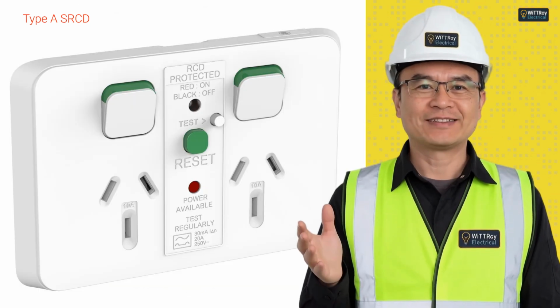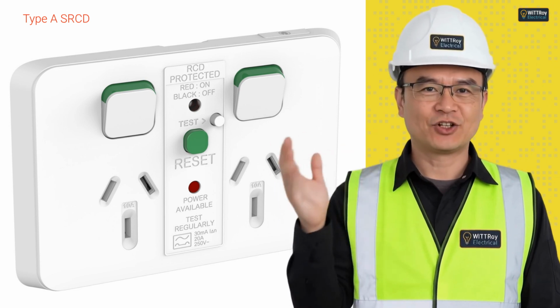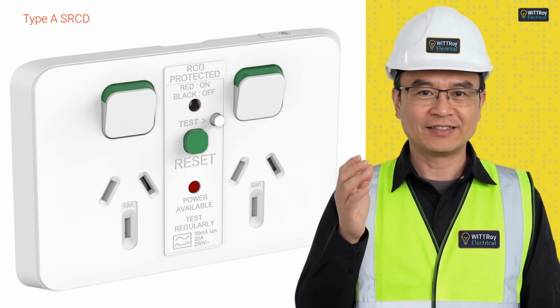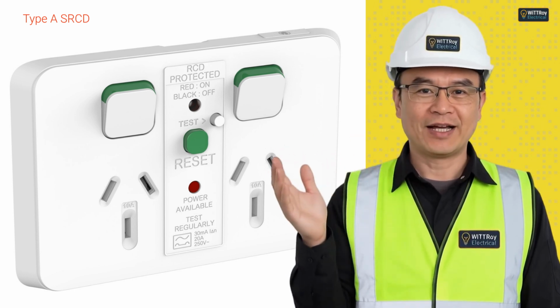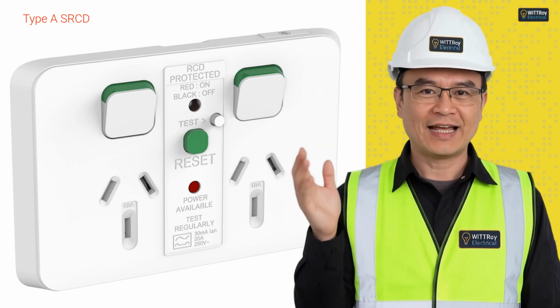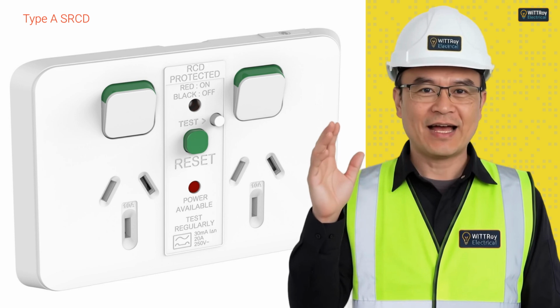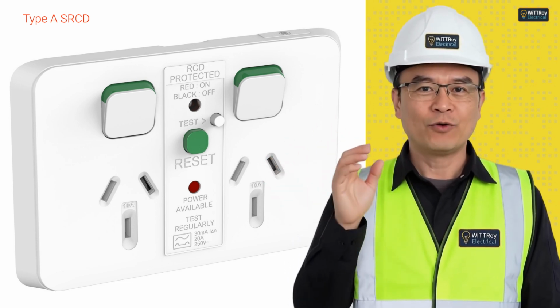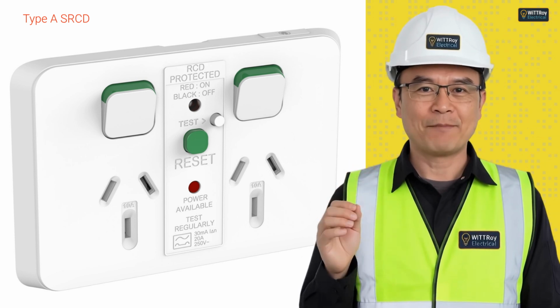Let's look at this device. This is an RCD protected socket outlet. It is also called an SRCD, which means socket residual current device. I can see RCD protected on the label. I can see 250V and 20A. I can also see I delta n 30mA. So this is a 250 volt 20 amp socket outlet with a built-in type A 30 milliamp RCD.